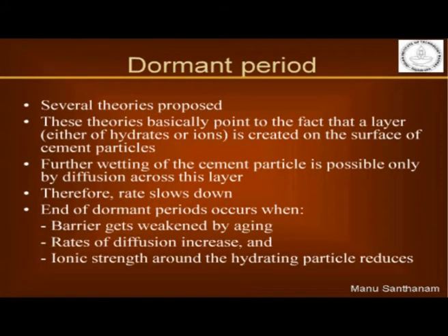So again, why does this dormant period occur and what is its significance? Please remember one thing, when you're mixing cement and sand and stone and water together to make your concrete, you need certain minimum amount of time during which you are actually working with the concrete, because you need to mix the concrete, you need to convey it to the job site, you're delivering this into the formwork, you're then compacting it, then finishing it.